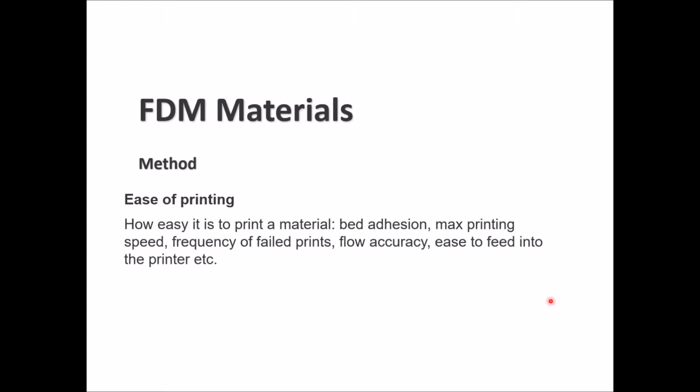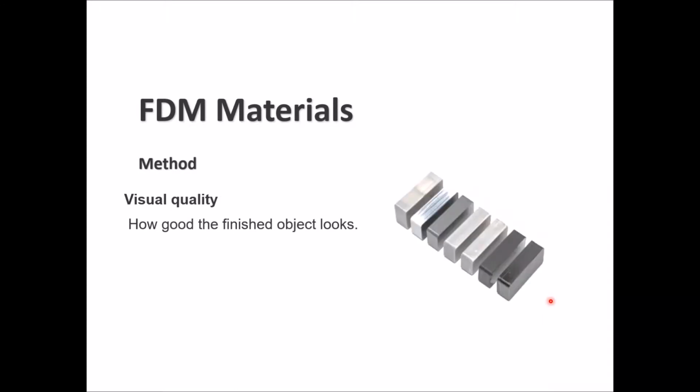As we said, how easy can you print this material? This involves bed adhesion, maximum printing speed, the frequency of failed prints, how accurate the flow is, and how easy it is to feed the material into the printer. I can add as well, how easy is it to get this material from the market? Is it available? Do you need to make extra effort to get one of these material cartridges or not?